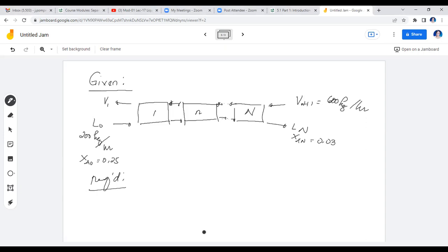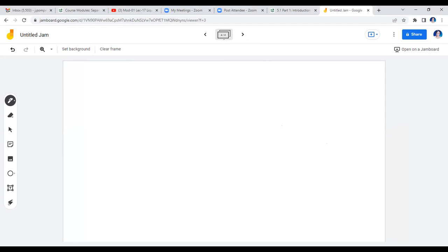So if you have none, then your required information is the composition and amounts of the exit streams. You have 2 exit streams, the raffinate and the extract. So it's asking for the composition and amounts of the exit streams. Okay, how do we do it? Go to the solution.